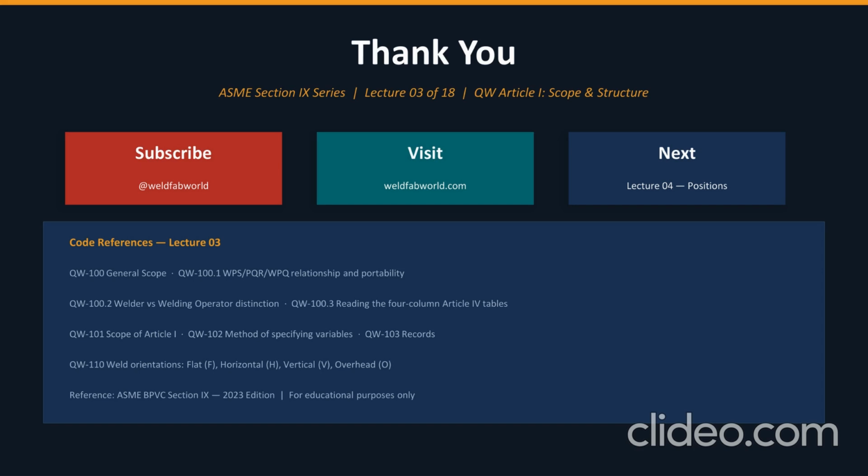Forms referenced: QW 482 for the WPS, QW 483 for the PQR, QW 484 for Welder Performance Qualification, and QW 485 for Welding Operator Performance Qualification, all in non-mandatory Appendix B of Section 9.